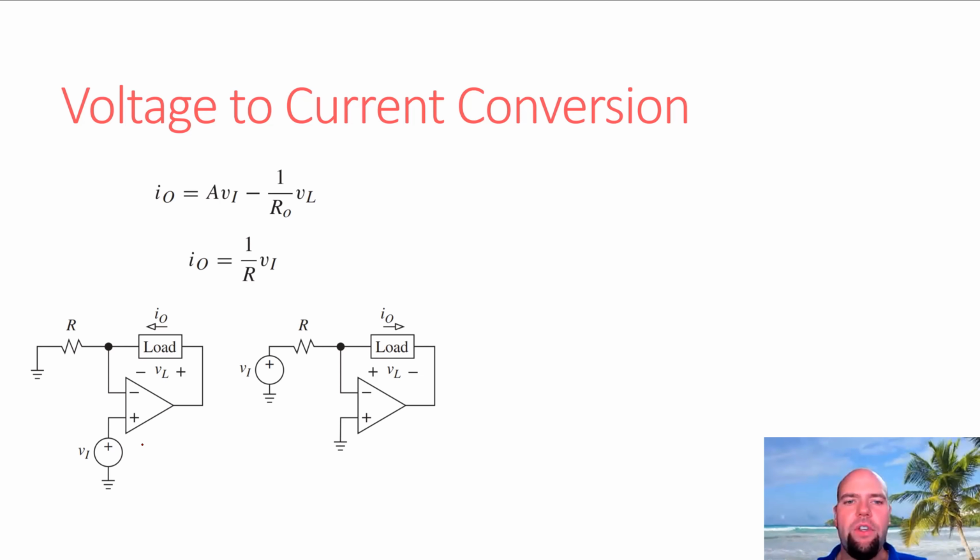And so usually it's easy for them to produce a voltage. It's easy for them to read a voltage. Currents, not so much. That's not always true, but usually not current. So if you're trying to generate a current that you can control with a microcontroller or something, generally you have to have the microcontroller produce a voltage and then convert that to a current.